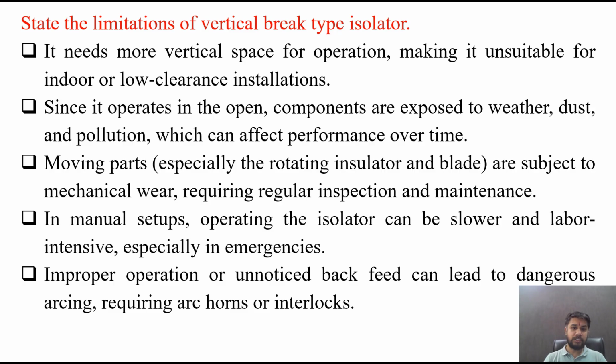In manual setups, operating the isolator can be slower and labor intensive, especially in emergencies. Improper operation or unnoticed backfeed can lead to dangerous arcing, requiring arc horns or interlocks. So these are several limitations or disadvantages of vertical break type isolator.